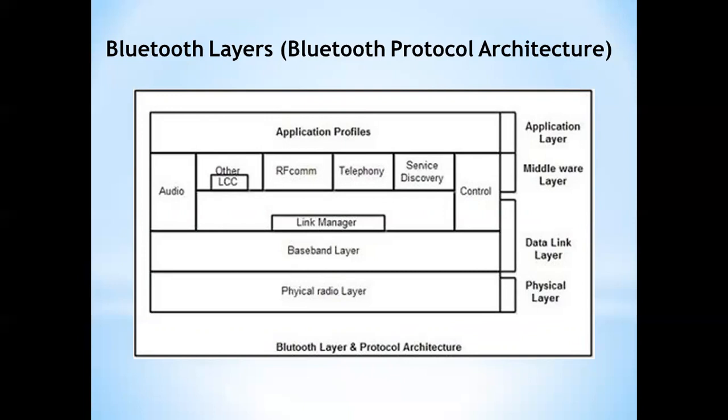Some other functions managed by the baseband layer are to manage the asynchronous and synchronous links, handle packets, and carry out paging and inquiry to access and inquire about Bluetooth devices in the area. The baseband transceiver applies a time division duplex (TDD) scheme used to transmit and receive alternately. Therefore, apart from the different hopping frequency, the time is also slotted.